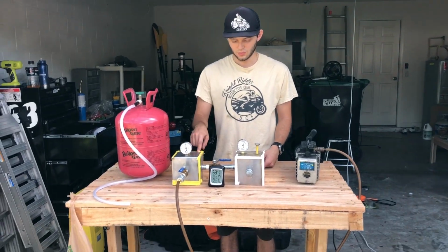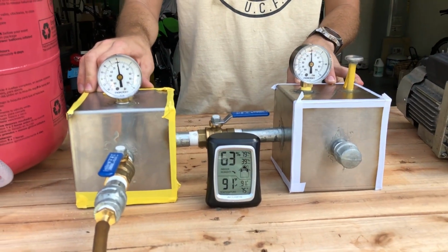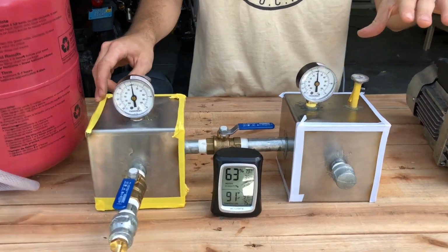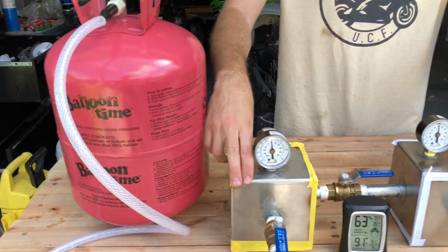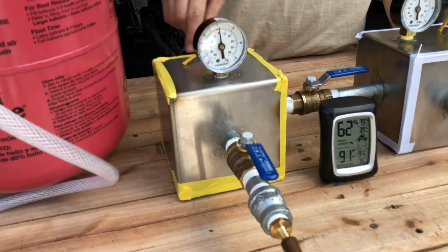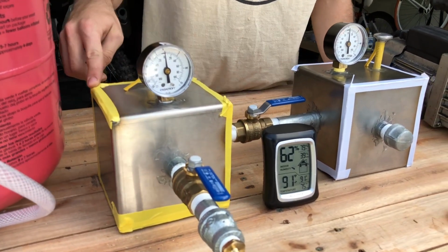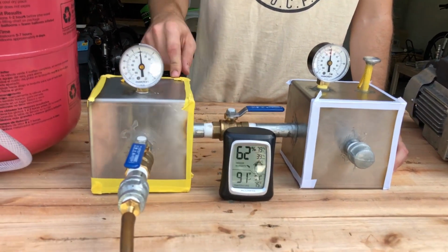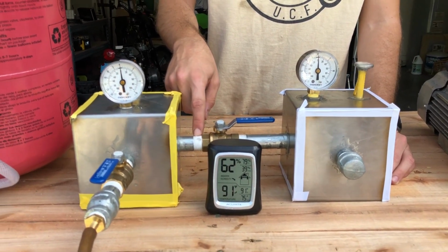Alright, so to replicate the real life scenario of the membrane problem, we have two separate chambers that are closed systems. They're separated by a valve in the middle. They're completely sealed off. One will hold a vacuum, the other one will hold helium of the same volume. And the way that we went about this is we have stainless steel that's completely welded and epoxied closed, so we have a complete vacuum, and then just extra tape for some protection. We did this by laser cutting it and then bent some of the pieces and had the rest of it welded into place and epoxied the pieces. We have Teflon tape to seal the threads on it,